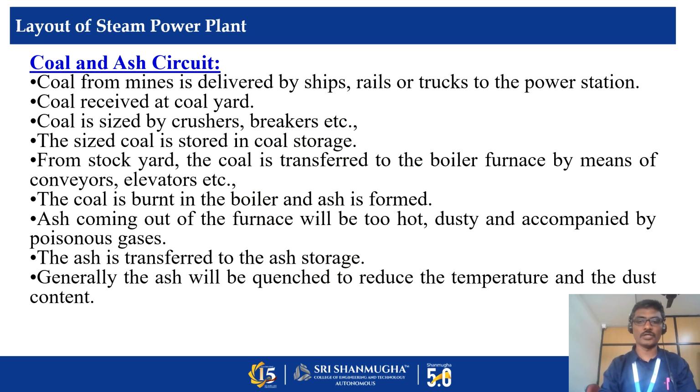First one, coal and ash circuit. Coal extracted from mines is delivered by ships, rails or trucks to the power station. Coal is received at the coal yard. Coal is sized by crushers, breakers, etc. The sized coal is stored in coal storage. From the stockyard, the coal is transferred to the boiler furnace by means of conveyors or elevators.